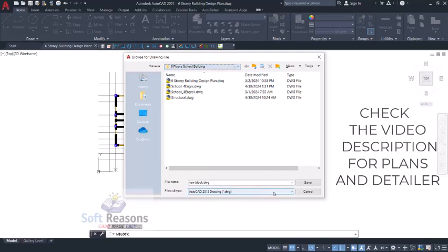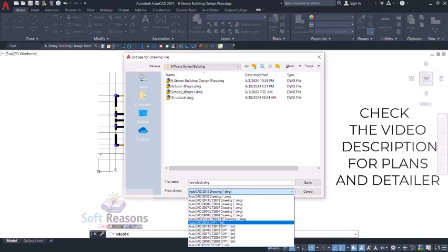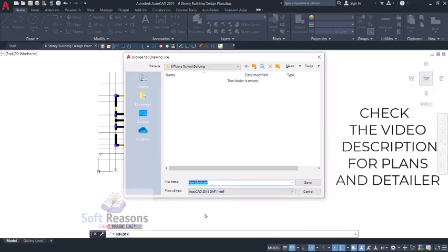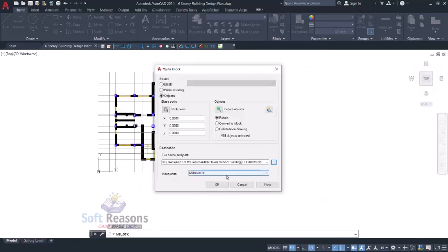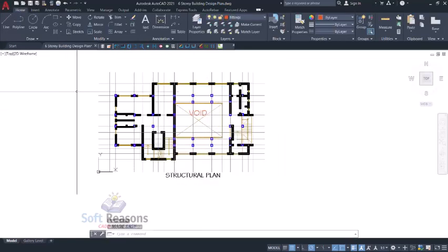But you come to file of type, options, and then in the drop down menu we choose DXF. Okay, DXF. All right, and then we can write 6 floors as the name right there, just like this. 6 floors. After which click on the OK option or save options and OK to have it created. So the file is being created inside documents, 6 floor folder right there.